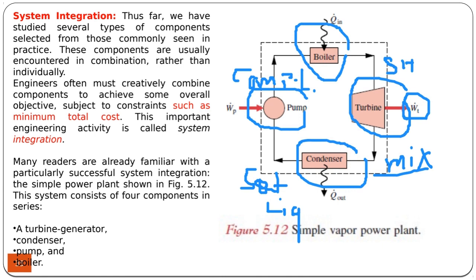It's a power plant which uses steam, the water vapor, to deliver power in the form of mechanical energy from the turbine. And this mechanical energy can be directly used as the power to turbine, power to propeller of a ship, or it can drive a generator, and generator can convert the mechanical power to electrical power.